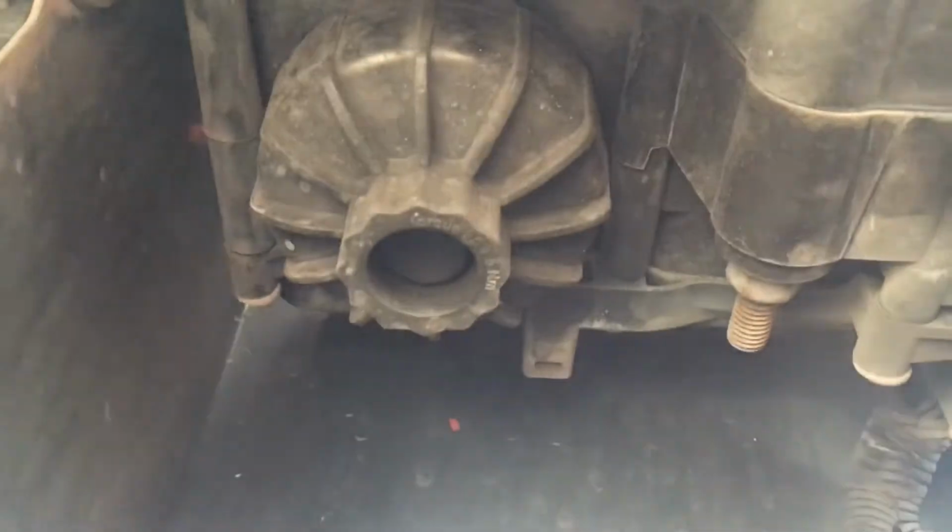Sometimes depending on the fluid level, it'll be strong in the odor of urea, or it won't be, but you don't want to smell diesel or anything else, and we'll be testing the quality of that in a different way. But you want to get under here on the back of your DEF tank, or your DEF lines, in your pump, in your DEF filter housing, and we don't see any crystallization or leakage or damage.